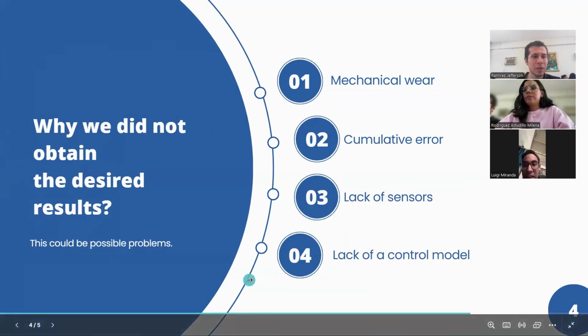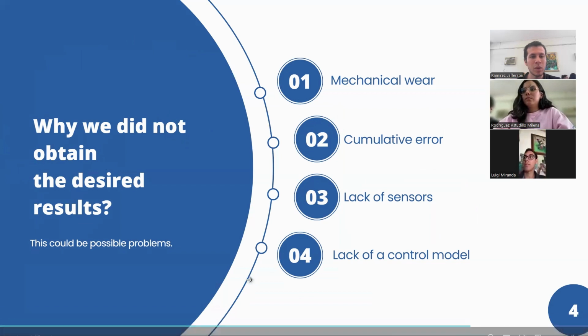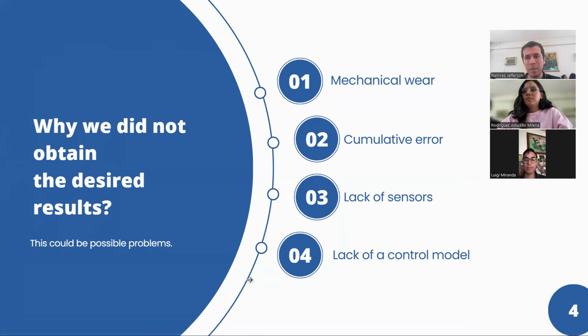Through experiments in a controlled environment, we know that odometry is useful, but is limited by various factors, such as a bad measure of the wheels and the distance between the wheels. Also, errors can accumulate, and the mechanical work can cause a significant deviation from the desired trajectory of the robot.